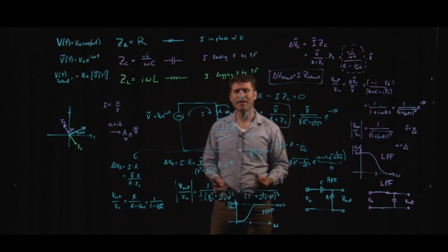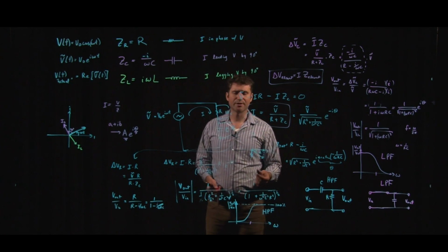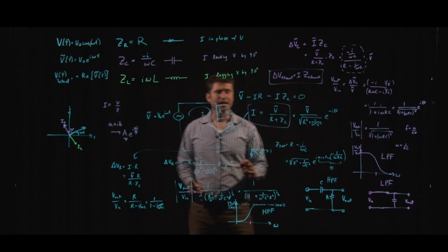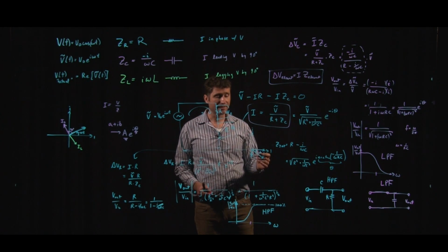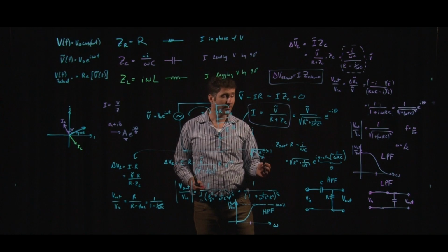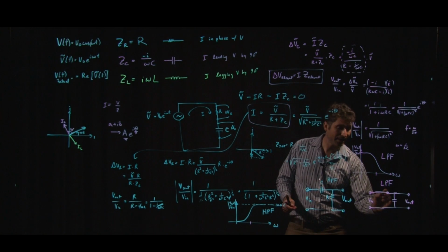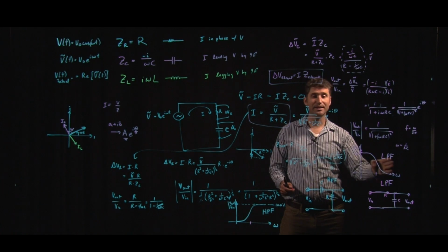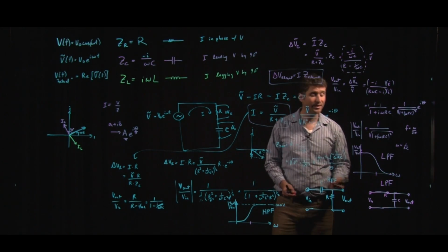So for example, imagine that you were using the wall voltage, which is 115 volts RMS at 60 hertz. And so you have a 60 hertz signal, and let's say you want to get rid of that 60 hertz. Well, then in that case, we should use a low-pass filter. So simply by picking the right resistance and capacitance, you can actually choose to only let through, for example, low frequencies that might be lower than 60 hertz.